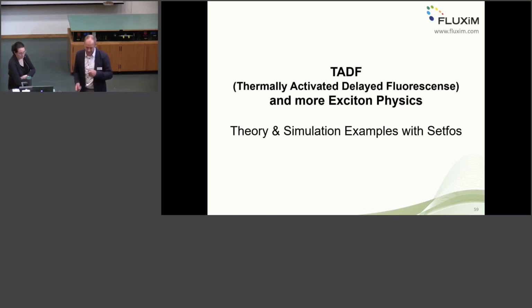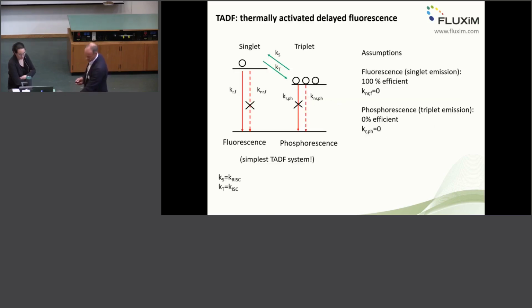And there's a section in this presentation where we discuss a bit more the excitonics. TADF emitter molecules, or TADF OLEDs, are a hot topic. Here we implemented, we have an example. What we implemented is having a transfer rate, an intersystem transfer rate. We call it KT because we're populating the triplet state, but we also have a back transfer, which is the reverse intersystem crossing. We call it KS, back to the singlet. And while one of them is a constant, the other one is a temperature-activated process. So if we run a temperature-dependent simulation, the transfer rate is increased at higher temperatures.